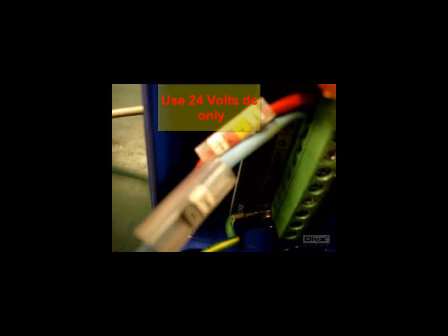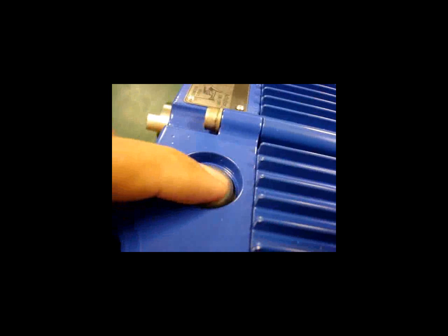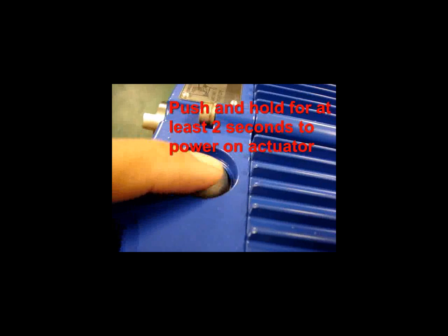First step is to connect the power supply terminals of the actuator to a 24 volt DC power supply. Then you turn on the actuator by pushing the green button and holding it for about 2 seconds.